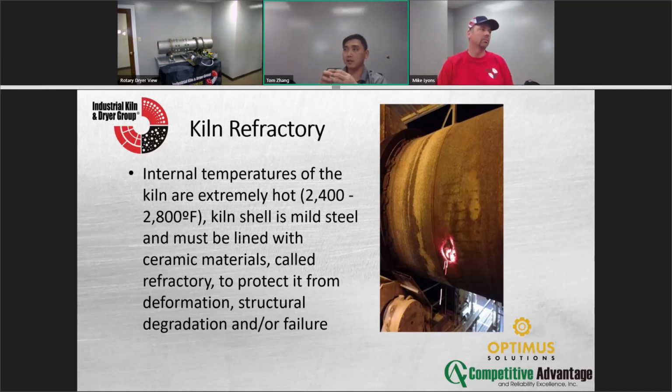So ovality, it's got the word oval. The opposite of the perfect oval is a circle. If you have a perfect circle in the kiln and you brick line everything with brick, it's not going to break. If you have an oval and you build an arch and you deform it a little bit, everything falls down. That is ovality in the most basic, generic sense. And that's something you can get done on a regular basis too.